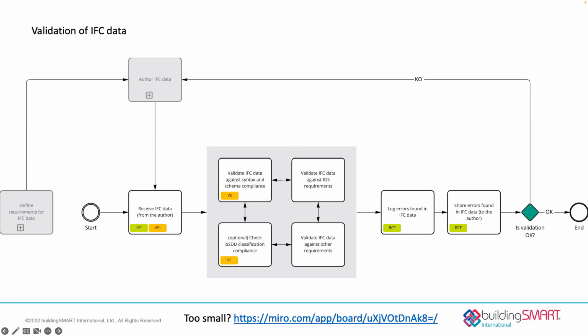Yes, it can. Yeah, so the original MVD requirements, those were very use case specific, where you said, for this use case, for precast, I always need these entities and properties as well, and I want certification to be sure that my software tool can support that. New certification is not doing those use case parts anymore, at least not at the second level. We still want to support that, but in a different way. Yeah, this is going to be complex, right? I'll dive into the details tomorrow. But IDS does have the ability to support multiple, basically define your own use case that is separate from some defined use case.